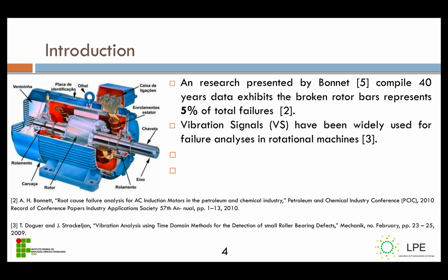Research presented by Bonnet, compiling 40 years of data, exhibits that broken rotor bars represent 5% of total failures. Vibration signals have been widely used for failure analysis in rotational machines. At first sight, this might not be such a representative percentage. However, due to the total number of electric motors, 300 million, even a small percentage accounts for a large number of equipments. So broken rotor bars should not be overlooked.